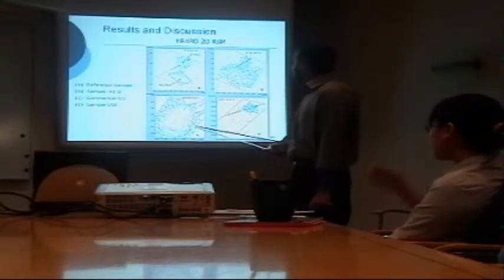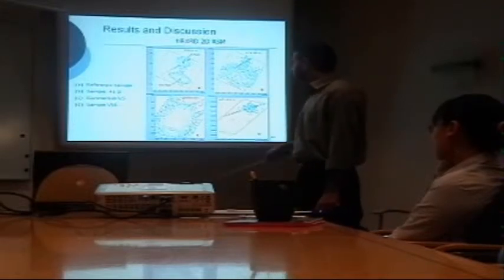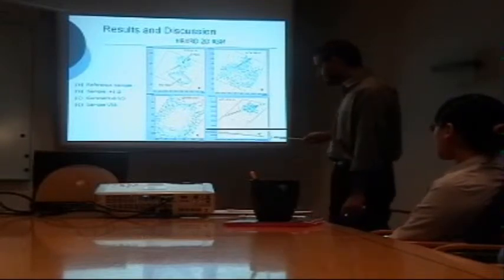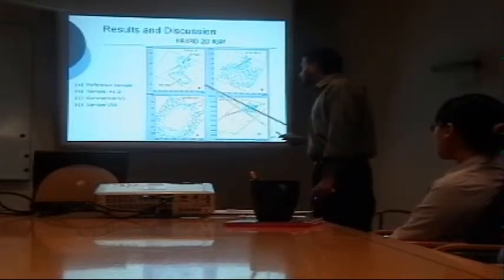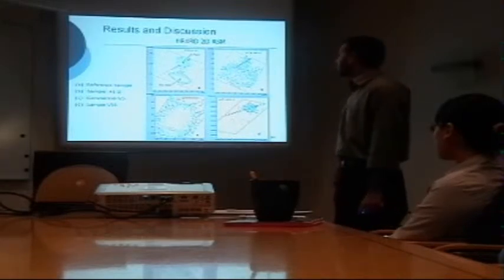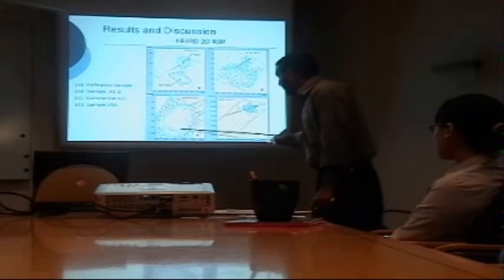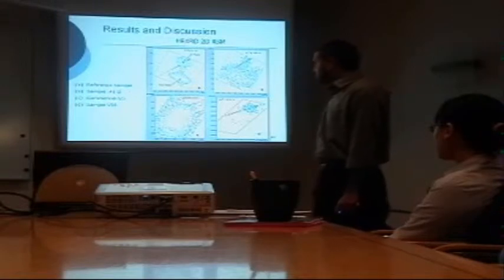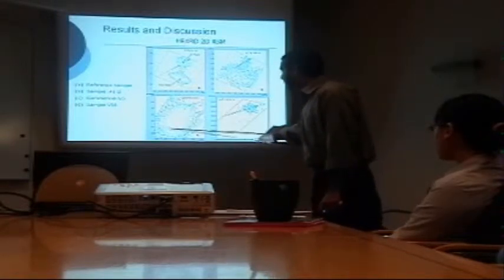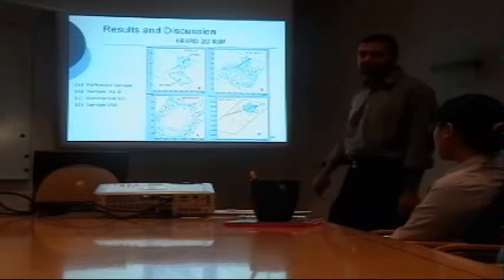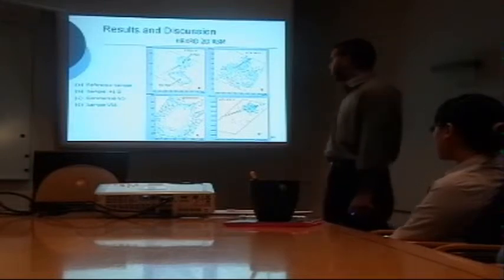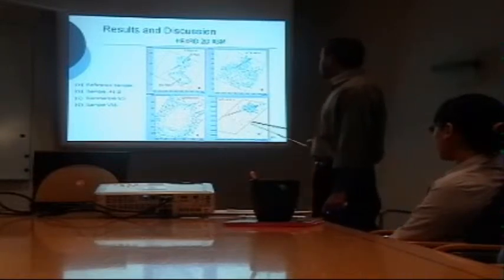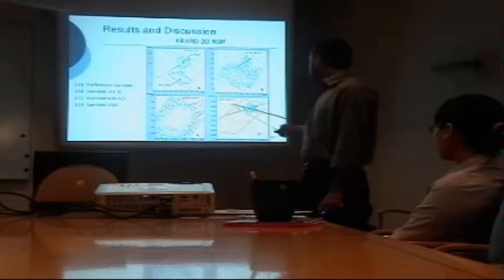In figure C, we can see the reciprocal space map from the commercial virtual substrate with 20% germanium concentration. So we can clearly see that the surface of this silicon germanium virtual substrate is fully relaxed because the silicon and silicon germanium peaks are aligned along the 113 direction, and we can clearly see the silicon and silicon germanium peaks, indicating a good structural quality of the surface.